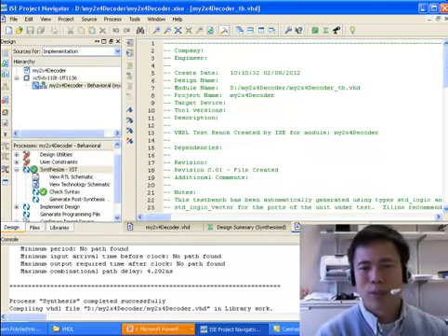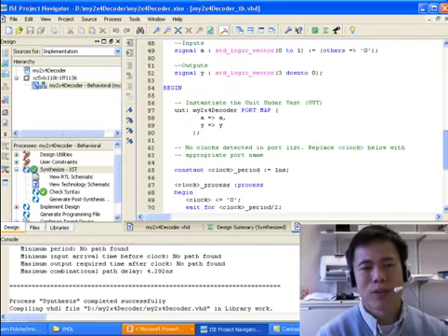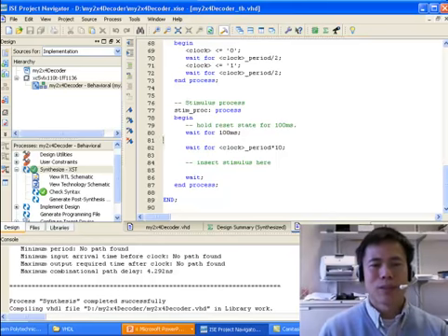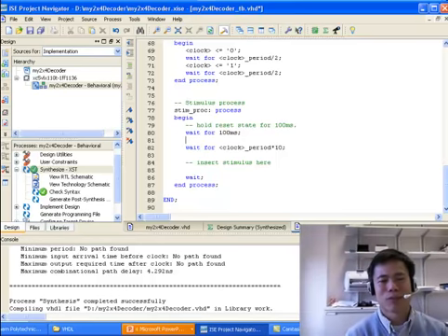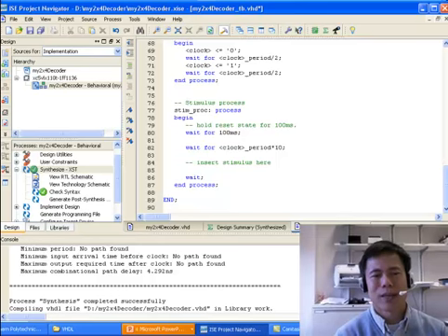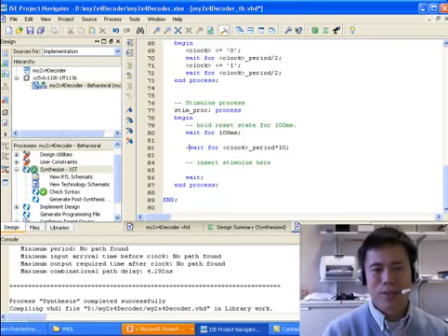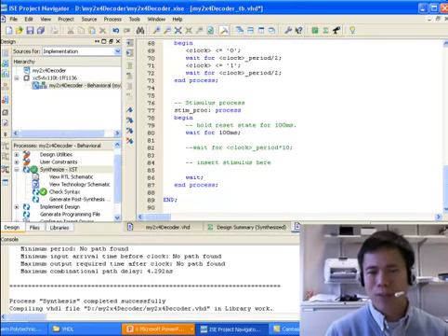The system will give you a test bench file in VHDL. All you have to do is scroll down to the process for the stimulus input. Here we first wait 100 milliseconds. That's the system suggestion for the input. Since this is combinational logic, we don't need a clock, so we can comment this out. Then we start giving the input.